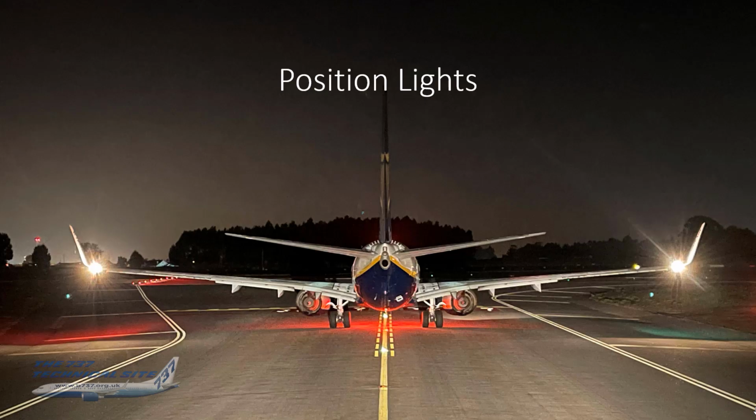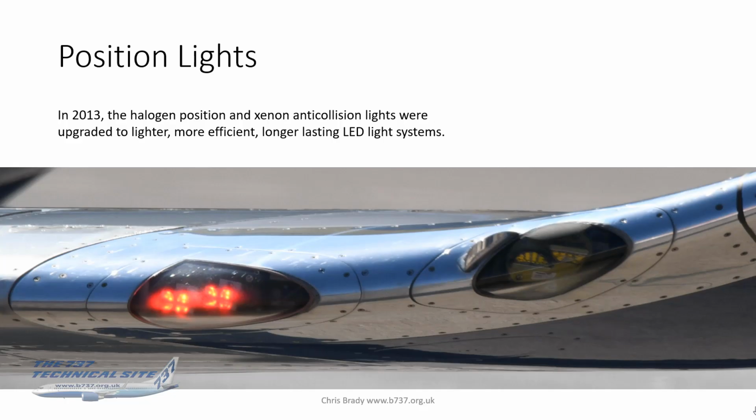Position lights, you can see a pair of white position lights there on that photo. Again, since 2013, same old story. Halogen position and xenon anticollision lights were upgraded to the lighter, more efficient, longer lasting LEDs. That's a little close-up photo there. Again, you can see the dual lens arrangement. You can see the vortilon there, just in front of the strobe that I was talking about a couple of slides ago, just to help with dazzling, the slight aerodynamic benefit as well.